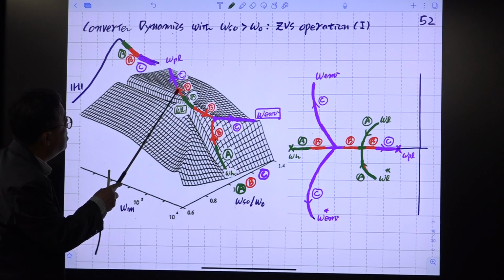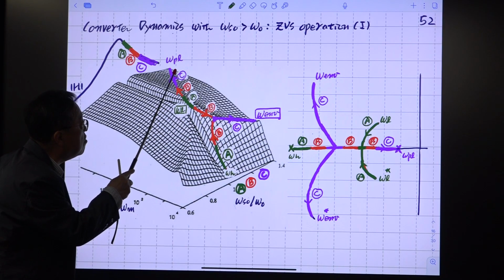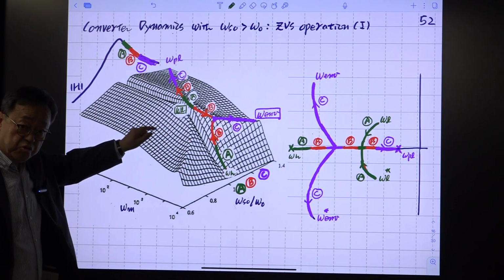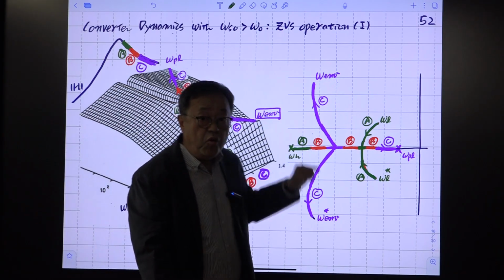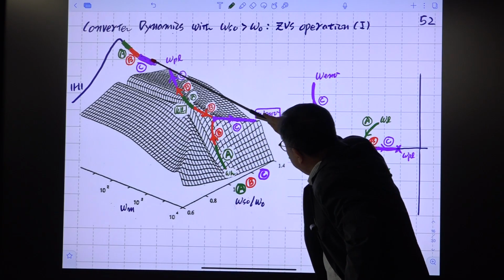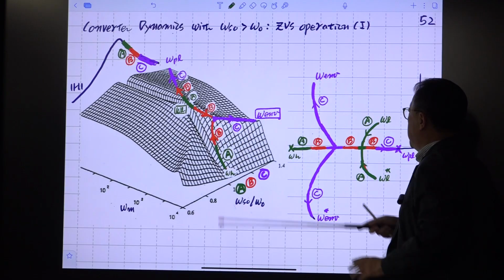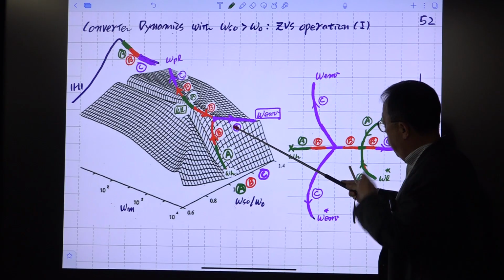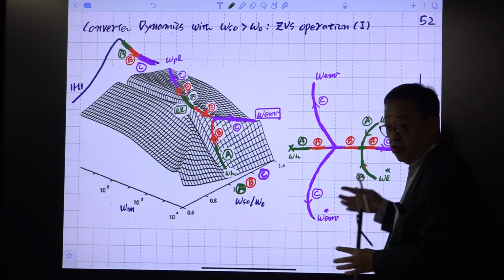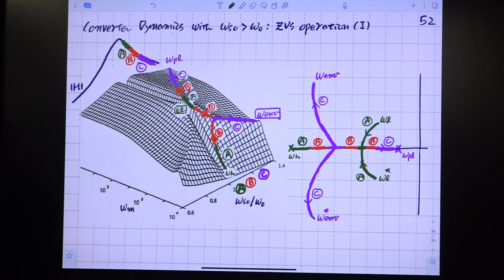Then this split dual pole moves to low frequency here, and these two poles are merging together, coupled into one double pole. And if you run down through this slope, or you run in this direction, then this omega E and B is increasing. This frequency is increasing, and the Q E and B is increasing. So it becomes more peaky, becomes peakier.